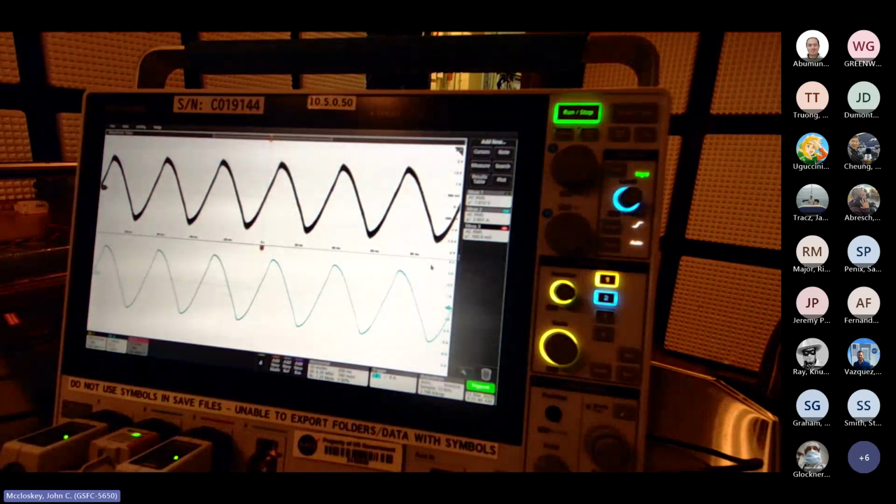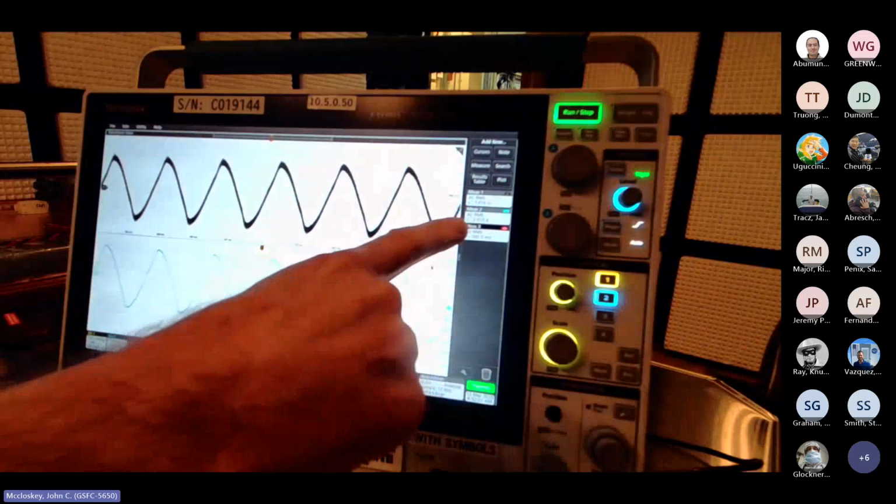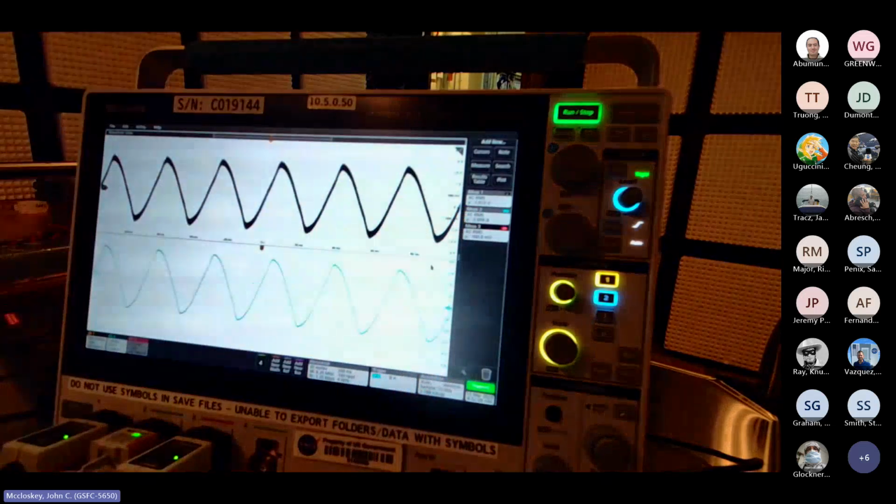use. Because if you just do RMS, then it's probably, at least some of the scopes that we've used, will give you that 28 volt component as part of the measurement, and that doesn't help you. It'll tell you that you've got 28 volts RMS, and that's not what you're interested in. You only want the AC component. So this AC RMS is important once we're actually injecting into the unit under test, which we're working up to.